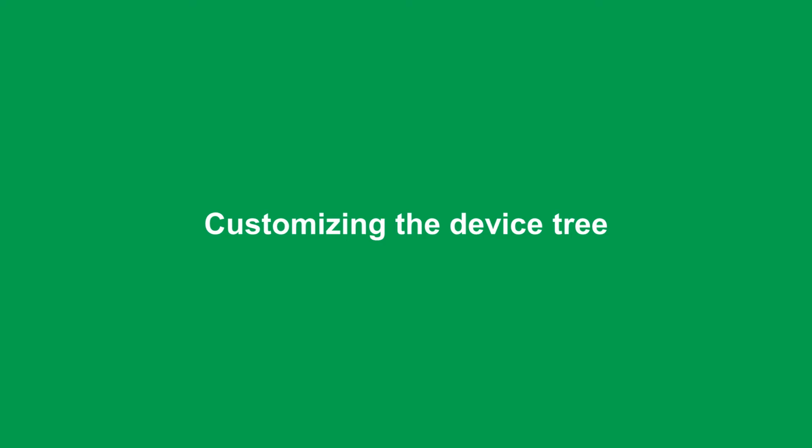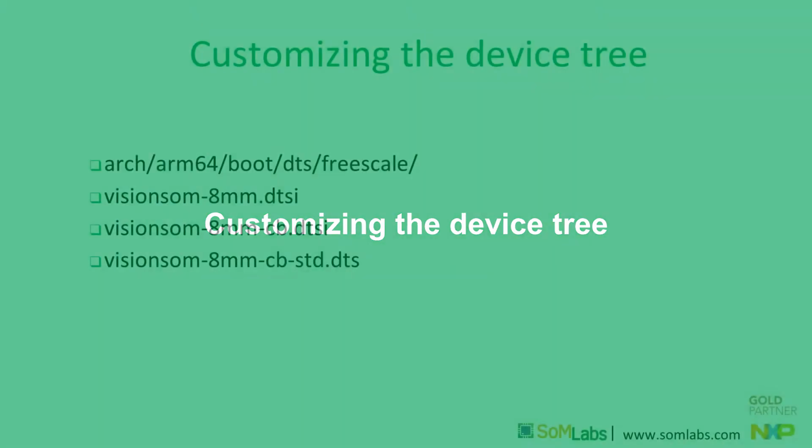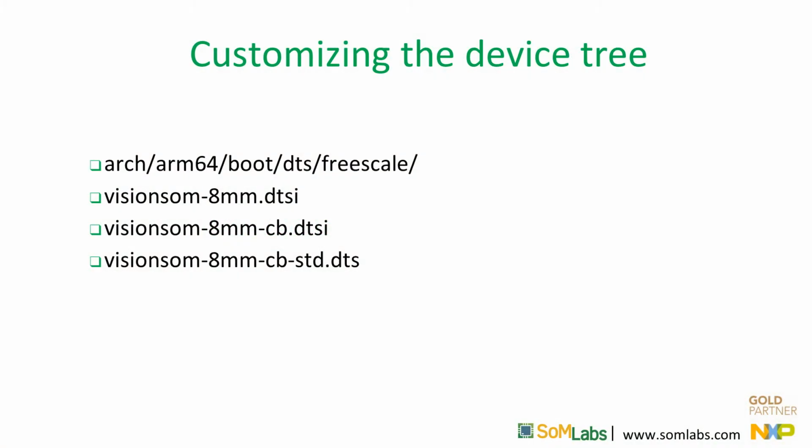Adding drivers to the kernel is not enough to keep the connected drivers properly handled and running. In the case of interfaces such as I2C, UART and SPI, we have to inform the system ourselves that the driver should be loaded and provide the necessary data for its configuration. This is what device tree files are used for, which next to the kernel file are an essential element needed to correctly boot the system.